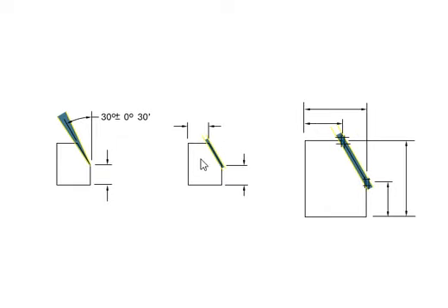Now we're going to make this diagram really big, so exaggerated like that, so you can see the endpoints of that inclined surface. So now you can see the tolerance zone is parallel to each other, so therefore it is called the parallel tolerance zone, and the polar tolerance zone is called that because it is a wedge shape. Okay, and it tells you the angle reference right here, showing you which is extended from this surface, extended from that surface. So you can see the angle right there very clearly. You can see the tolerance zone very clearly. Remove the imaginary lines out of it, and you're going to be left with two parallel tolerance zones. Okay, all right.